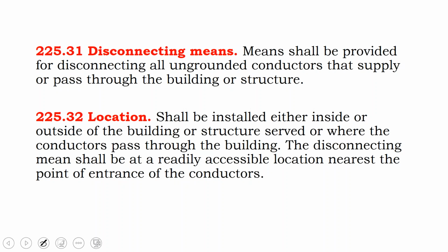And the answer is you put them in different locations. So they're both readily accessible, but if you have a backup system or emergency system, you have to put it physically separated from your mains, so that if you're just turning off all your mains, then you have to walk, and it might just be a distance of 10 feet, but something where you have to have an intentional act to go to a different location to turn off your backup and standby. So now we have multiple services coming into the building, not just for your main power supply, but also your backup and standby supplies.